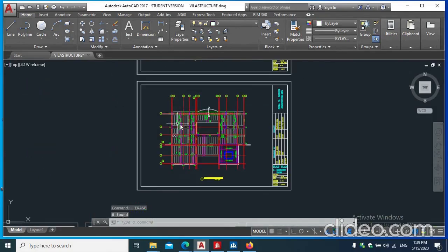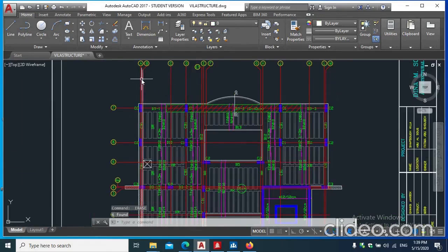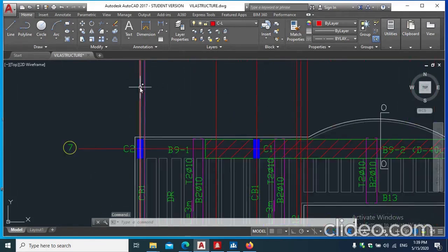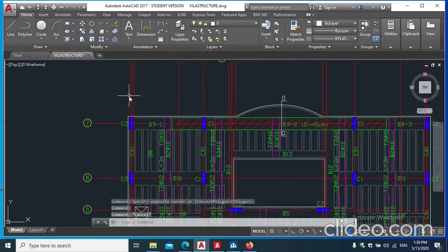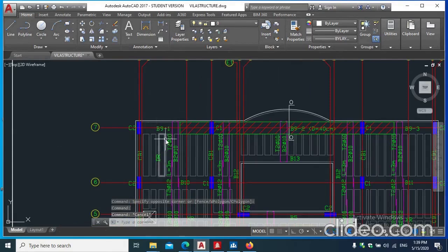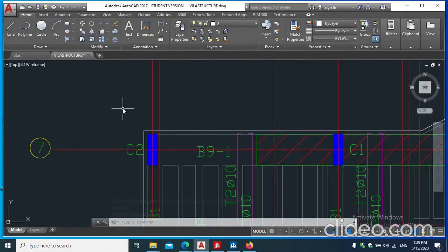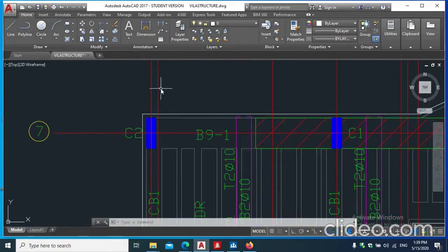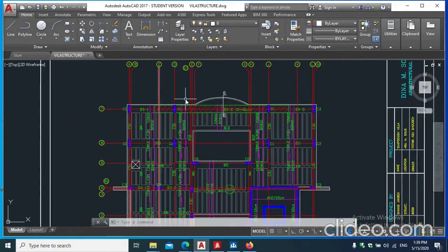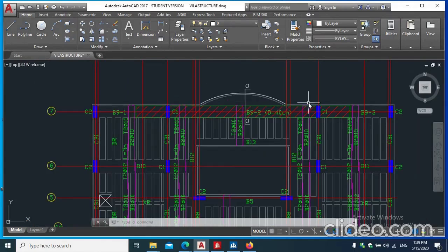We'll clean them up and move to the grid here. For example, now our grid has become separate lines. To simplify it, you'll find many lines that might not be necessary for you as a structural engineer, because some lines are for the architect. So, you want to simplify it and start with a basic grid.